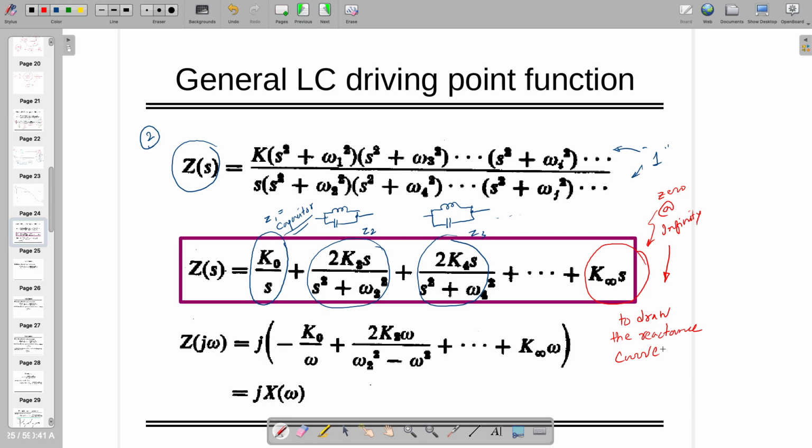It is giving 0 at infinity. It may be 0 or pole. Anything can be there, right? If something is available at infinity, which might be much beyond your UGBW, then whether you are keeping 0 or pole, it doesn't matter. You can keep anything. It may have infinite number of poles and infinite number of zeros available at infinity,